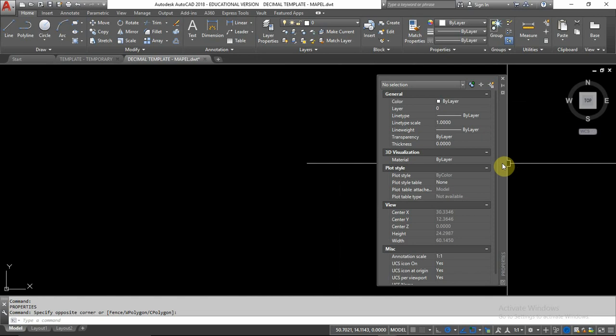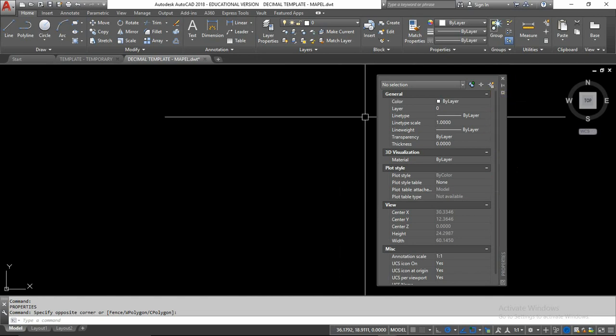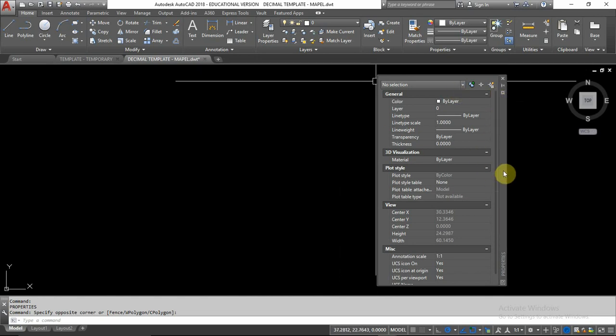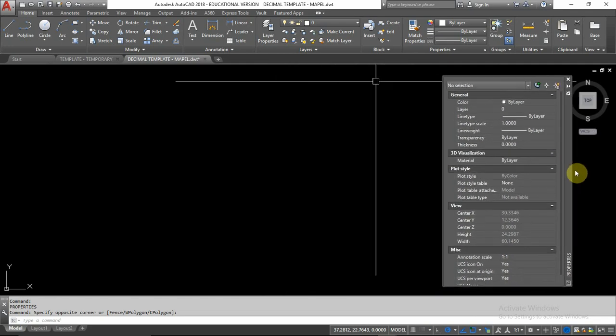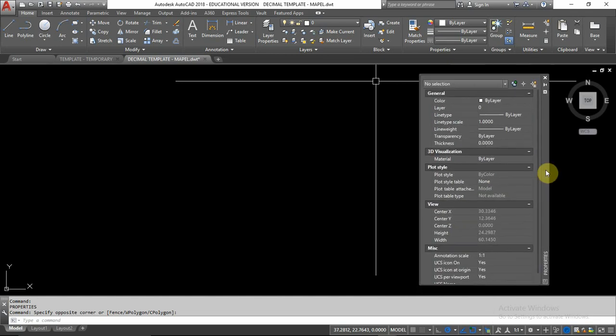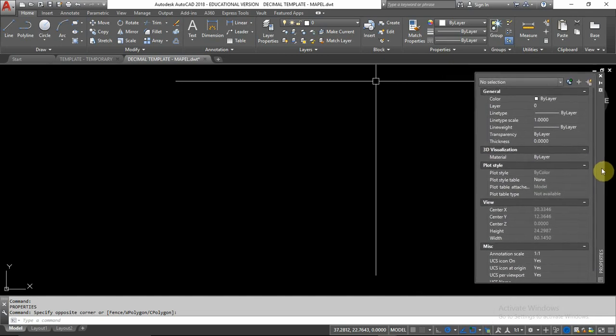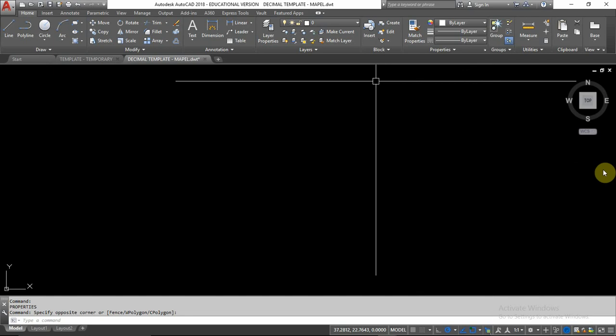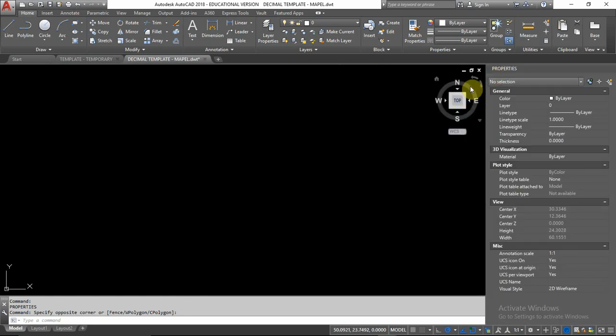Another thing, grab this window. Don't be surprised if this window is not on your right. It might be on your left. It might be at the top. The reason for that is because I can put this somewhere. Now pay attention to what happens to my screen when I get there. As I get to that right side, notice it jumps to that entire window. And if I let go, there it is. Notice my view cube, nothing was blocked. Everything just moves over. It also doesn't block the status bar down below. It's not in front of my ribbon here. And the window title, in this case Properties, as well as the auto hide and close, is now at the top.